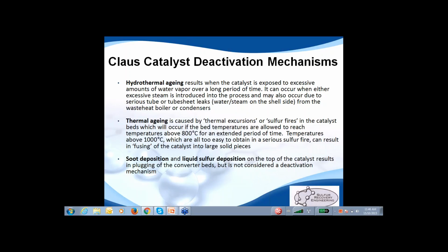Soot that forms and sets up on our first catalytic reactor bed, upon restart of the plant, we will see a high pressure drop across the converter. As a result, we wouldn't be able to process as much process gas as we are supposed to. Thus, it's always highly recommended to conduct a proper SRU shutdown and or startup in order to reduce the risks associated with additional downtime coming out of one of these events to clear the soot from the first catalytic bed.